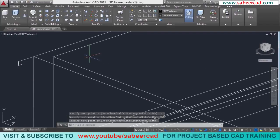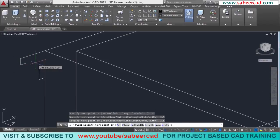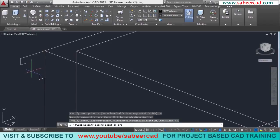Just give an enter to repeat the polyline command and I'll move 15 units downward, then 3.5 units leftward, then 3.5 units upward. Then I'll switch over to the arc option by right clicking and I'll click on the arc option. Then I'll go to right click and select second point and I'll choose a point somewhere over here as a second point. Then I'll click this as the end point.